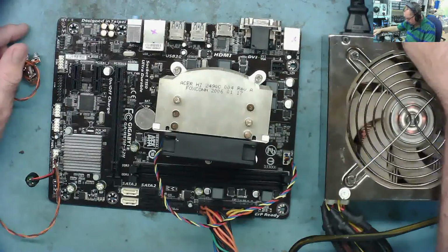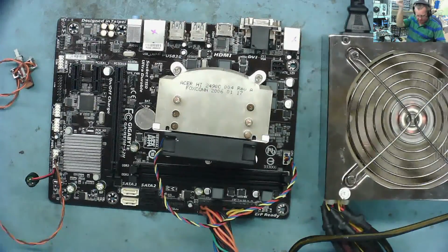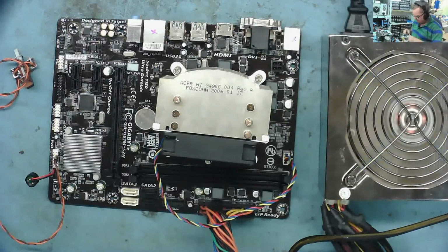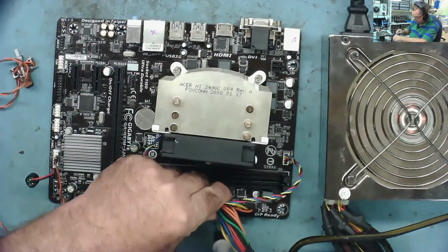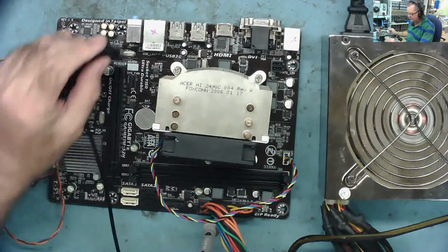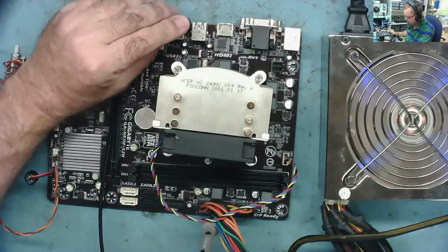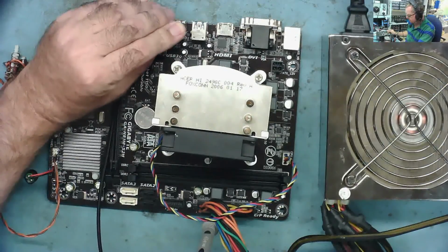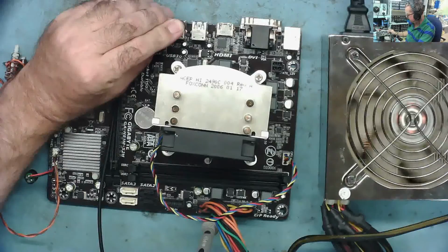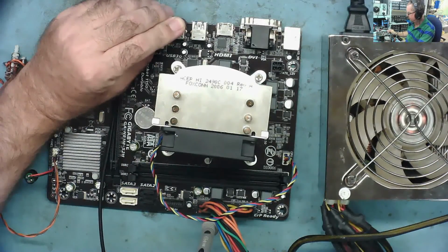I wonder what happens if we just force it to power up. So effectively we'll just connect the green wire to ground. Stick a meter lead in there, then we'll just ground it. And let's see what that does then. We'll let it start up and ground it. It still shuts down. And it stays off.